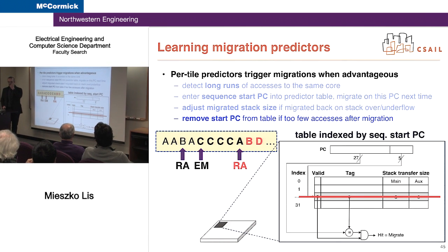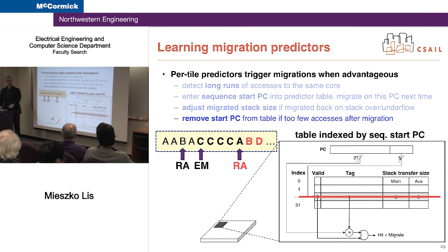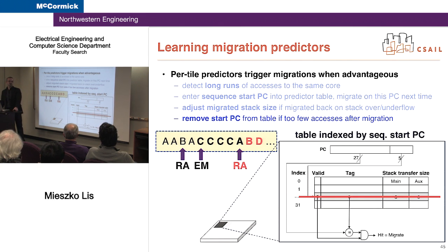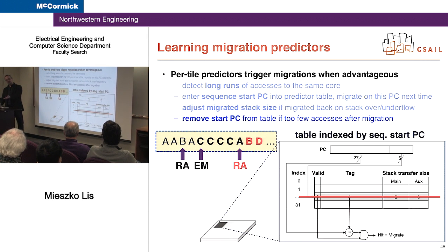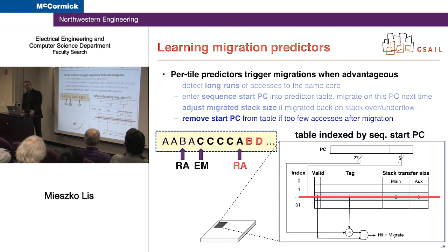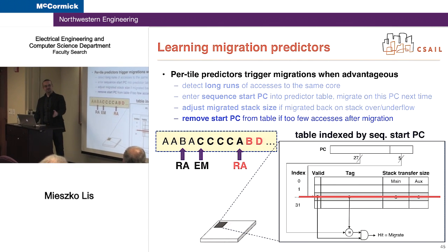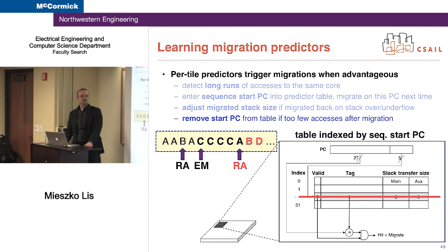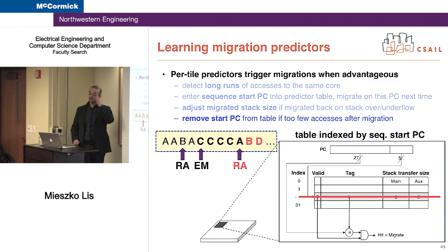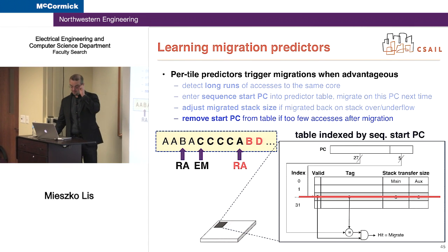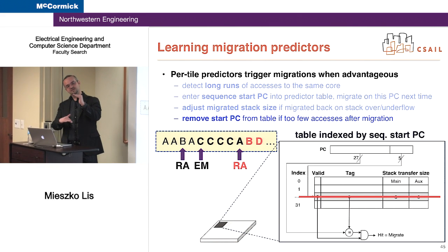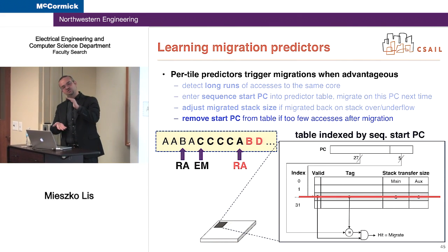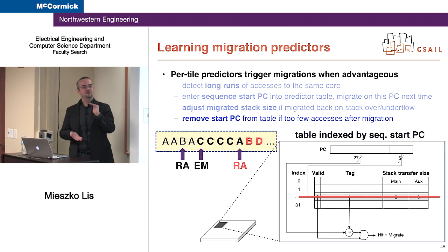So we have two ways of doing this. In particular, if you do a store, if you do a load, you have to wait anyway. But for a store, we have two kinds of stores. One of them is you wait for the acknowledgement, and the other is you say, "Forget it, I don't care about the acknowledgement." Actually, for most stores, you don't need the acknowledgement. You need it at a much rougher granularity than a single instruction.